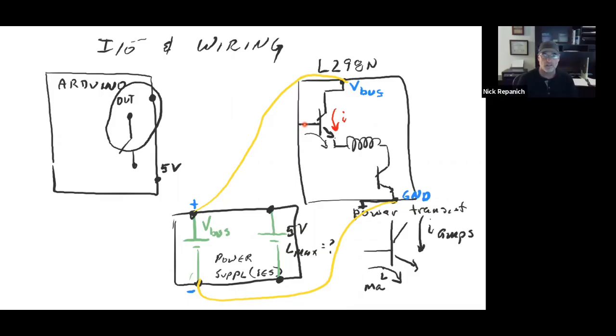Every single one of these is going to be power, switch, and load. So every time you draw a circuit, power, switch, and load. And then when you've got it, it's like, okay, nothing's blown up. Then you have one last thing to do, and that is how much current's going to flow in that.